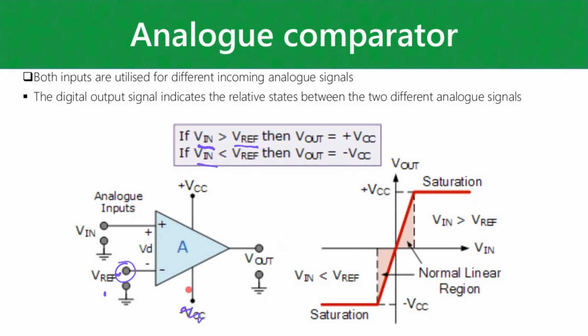And if you connect this part to ground, however, that's going to be driven to 0 volts. Right. So I think you guys can see this is actually a very nifty way to use an op amp to digitize a signal.